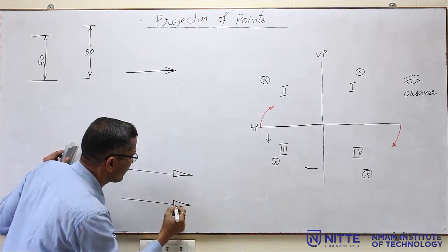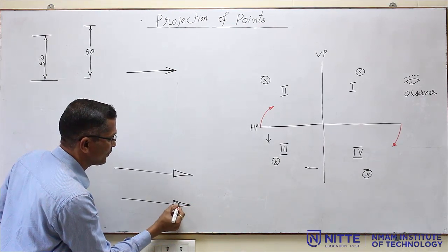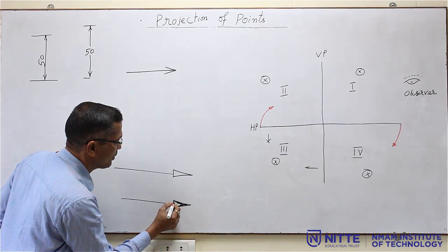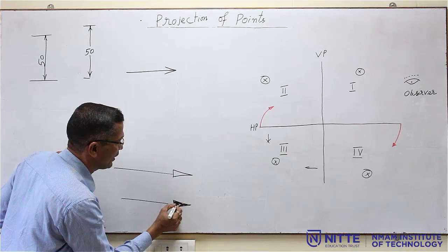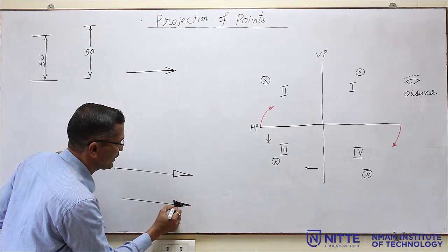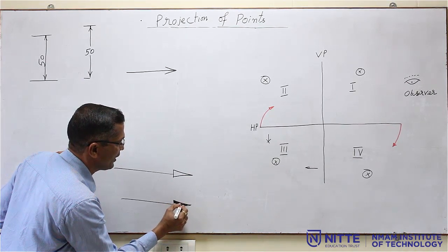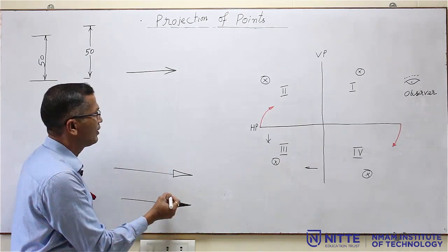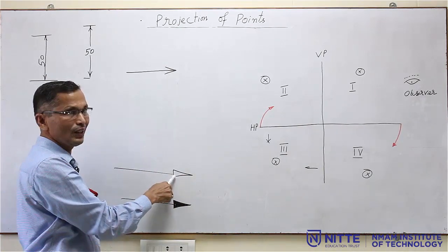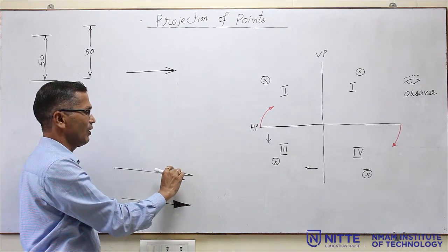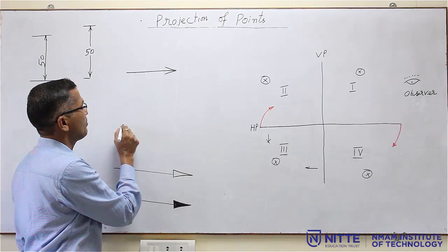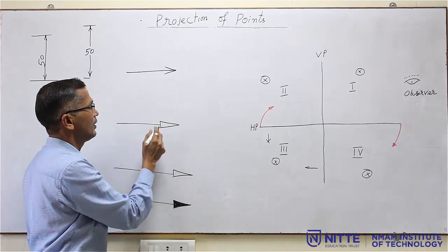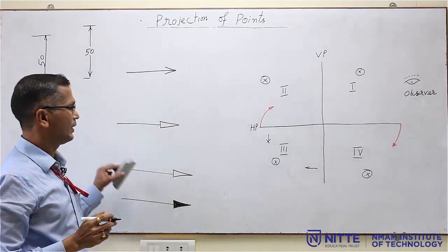If you are very good at drawing, then you can use the closed and filled arrowhead, but it should be very neatly drawn, then only it will increase the beauty of your drawing, otherwise it will spoil it. So, the filled arrowhead should be used only if you are very skilled. Otherwise, stick to the open or the closed one, because the ratio is very important. This is 1, this should be 3, only by practice. So, you have to practice drawing these arrowheads many times.